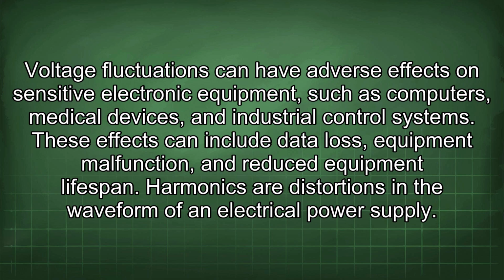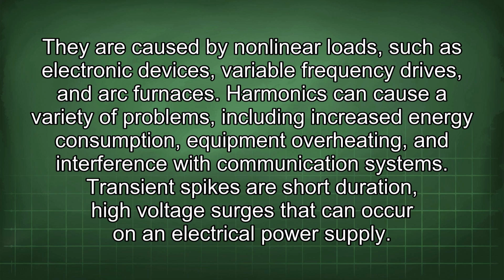Harmonics are distortions in the waveform of an electrical power supply. They are caused by nonlinear loads, such as electronic devices, variable frequency drives, and arc furnaces. Harmonics can cause a variety of problems, including increased energy consumption, equipment overheating, and interference with communication systems.